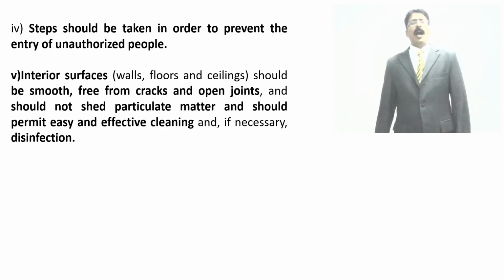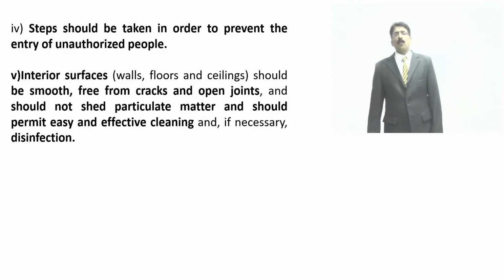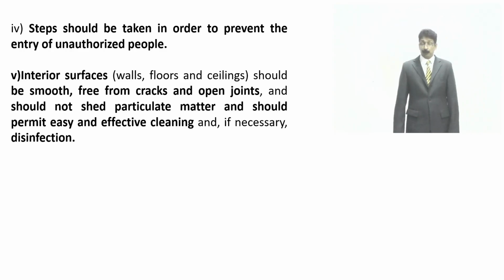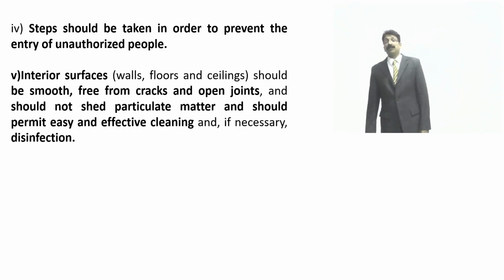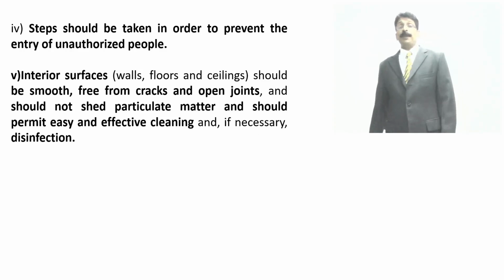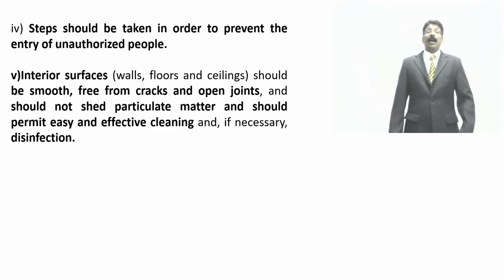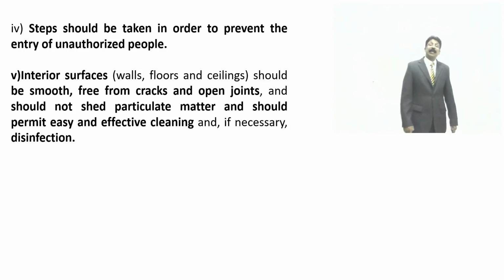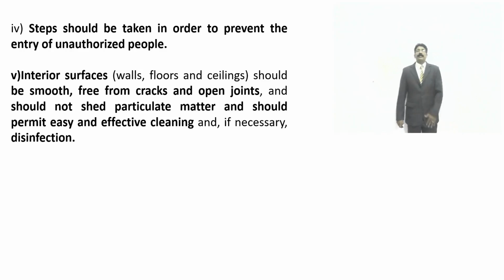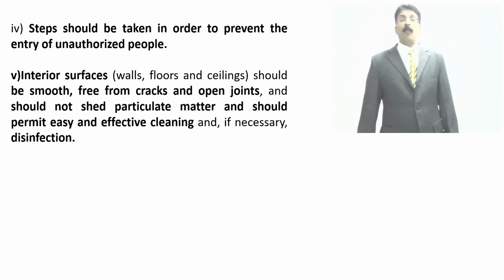And interior surfaces in construction, walls, floors and ceilings should be smooth. They should be free from cracks so that no dirt will go and stay inside, and open joints should not be there. They should not shed particulate matter, and should permit easy and effective cleaning, and if necessary disinfectant can also be used for cleaning all walls, floors and ceilings.